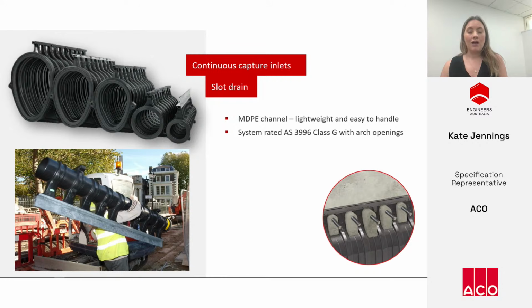The last system here are slotted drainage systems, and these are often manufactured from MDPE. This makes slotted channels really lightweight and easy to maneuver on site. So installing these channels is incredibly quick because you don't need cranes to lift them into place.